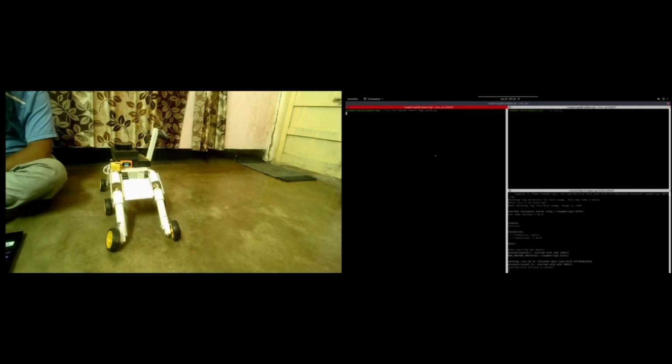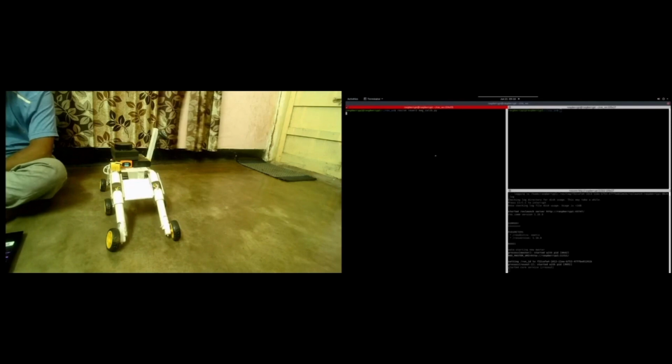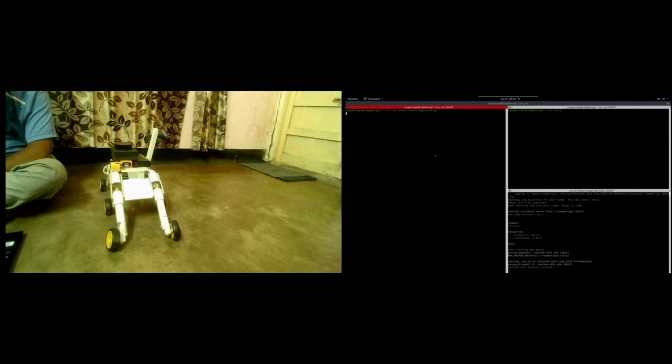A magnetometer gives us the input as the X, Y, and Z components of the magnetic field, influenced by the Earth's magnetic field at that point. But there are certain disturbances caused by soft iron and hard iron influence. In order to cancel out these influences, we need to calibrate the magnetometer values.